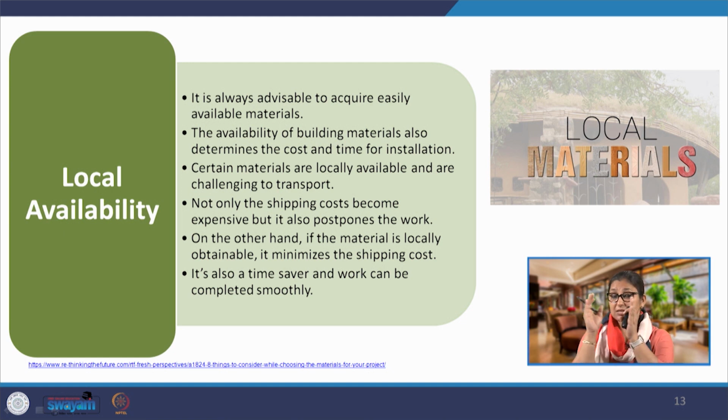The next one is this category which is broadly under the production and construction category, and here whenever we are talking about sustainable buildings or green buildings, we must look for materials which are locally available preferably, and there are multiple benefits of that. We are looking at it from the point of view of a client who owns the building or wants to construct the building. For us it will be cheaper, one, because there is less transportation cost. So, automatically the preference would be local materials, unless we have specific structural or performance requirements. That is from the client perspective.